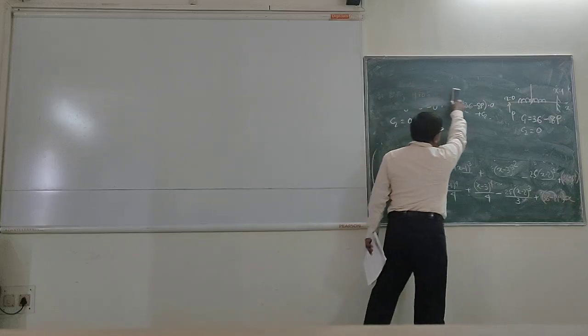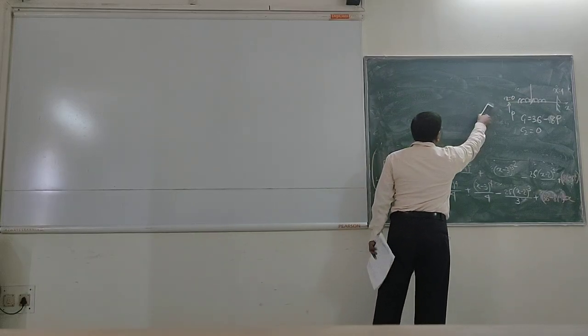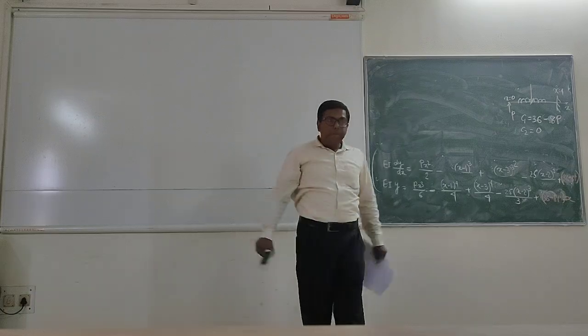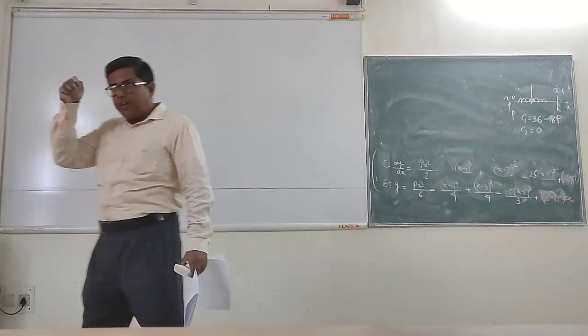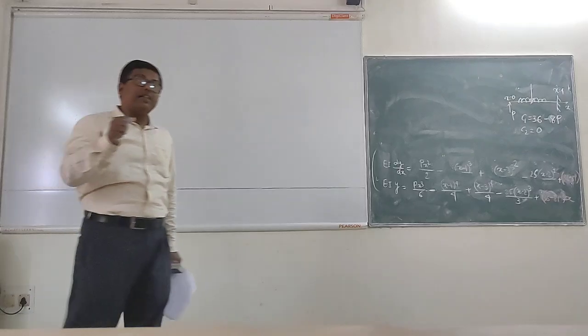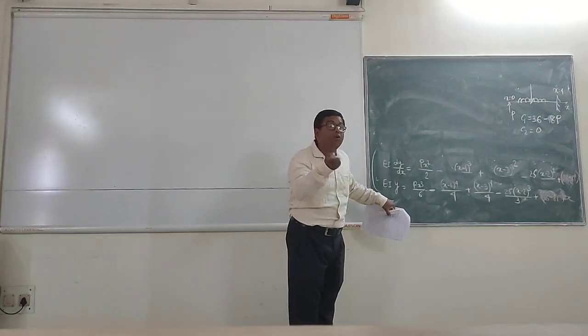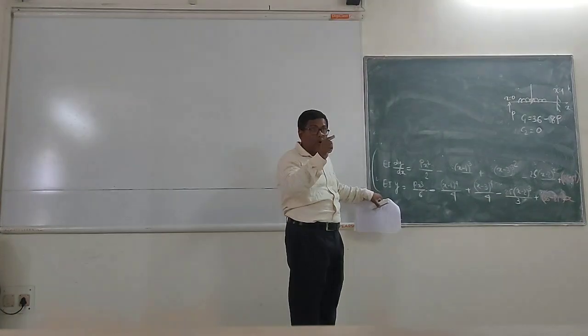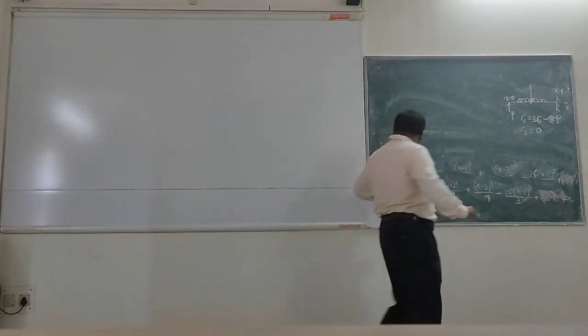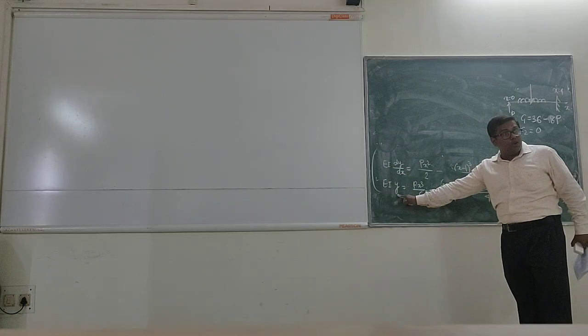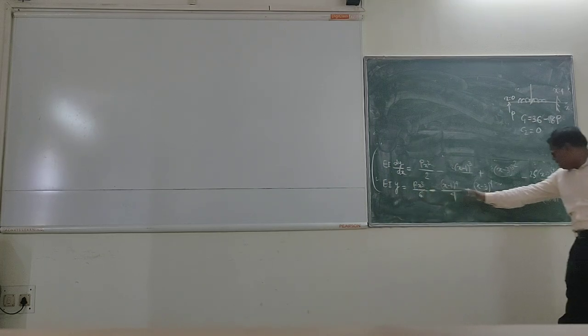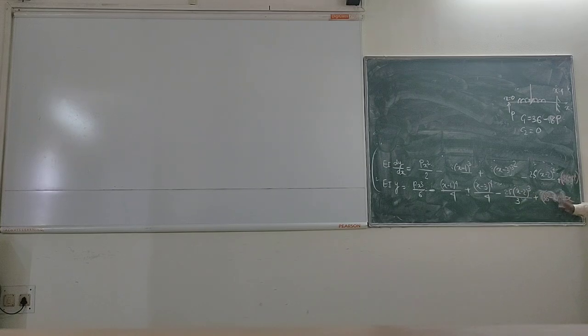So considering the third boundary condition, another very simple boundary condition, fixed end. At the fixed end, the slope is equal to 0 as well as the deflection being equal to 0. When I consider deflection equal to 0 at the fixed end, then y will be equal to 0 and x will be equal to 4. If I go into this equation and put in the value of x, you will have only one unknown, p, and you can find out that unknown p.